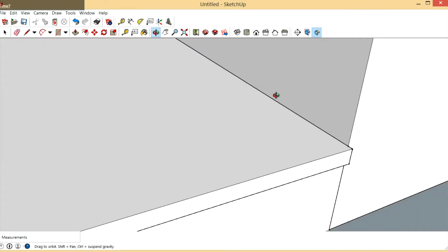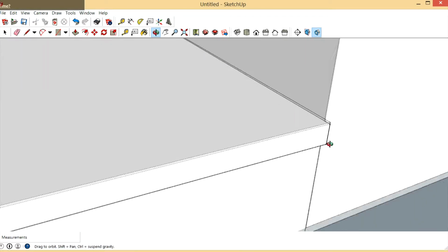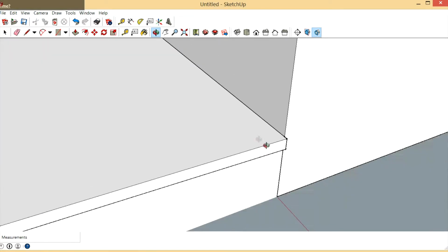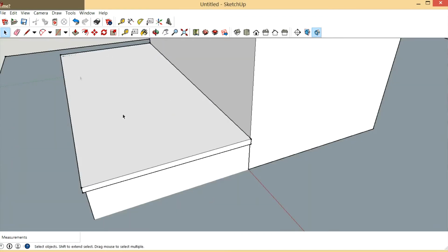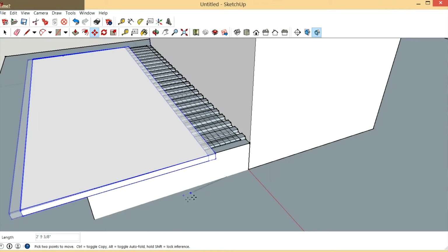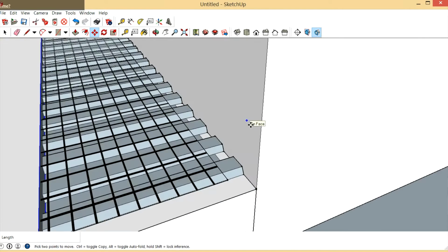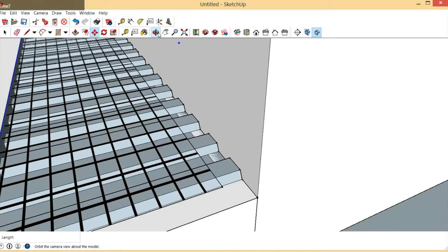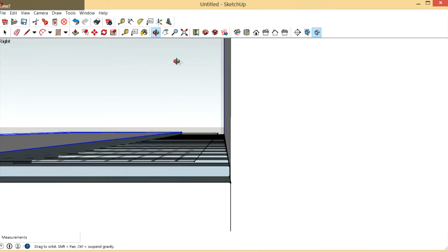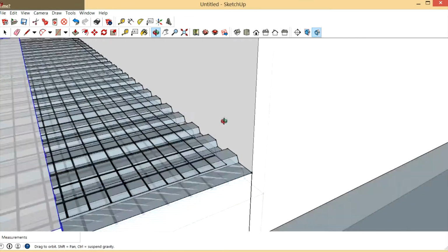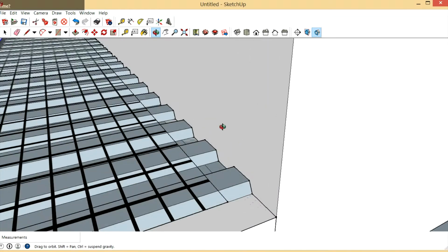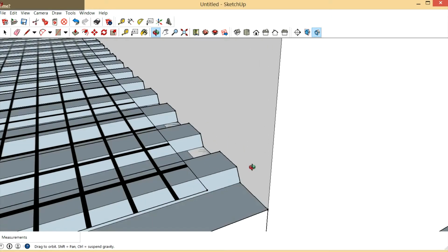So the flashing issue. Let's pull our slab back again. I'm going to grab it, find me a reference point somewhere, and just pull it back about 4 feet for now, and then I can move it back later. So really, if you were going to use a pan, I'd recommend putting your flashing on first.